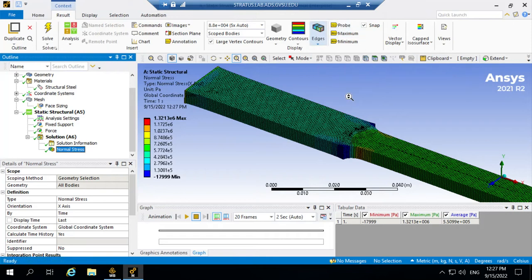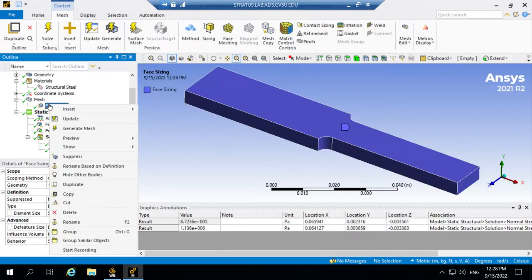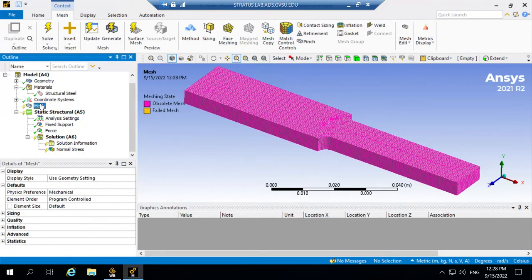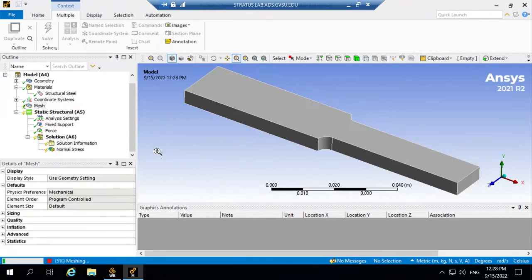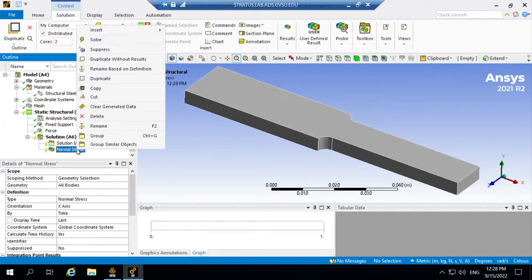But we know we are not interested in that section. We want to see what the maximum stress is where I know we have a stress concentration. So in that region, it has not changed much. Alright, so this was just a demo of how to do refinement. So I went back to that crude coarse mesh that we had at the beginning.